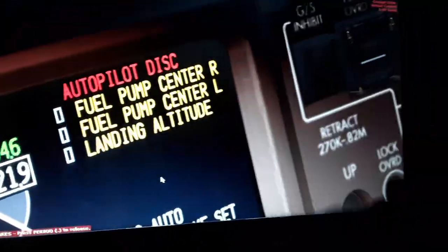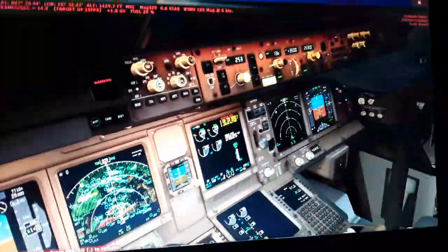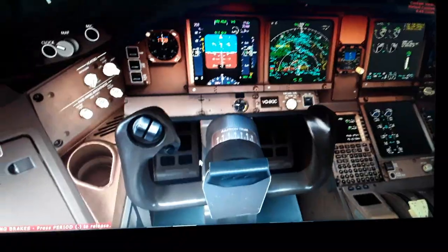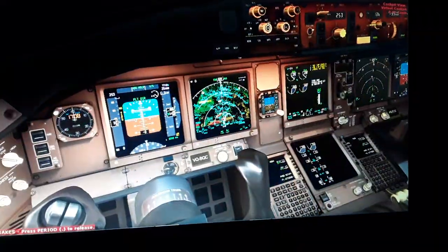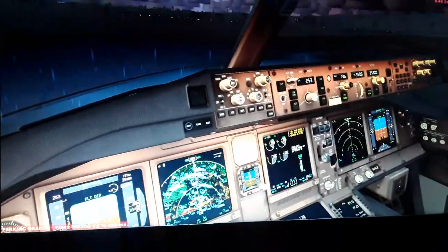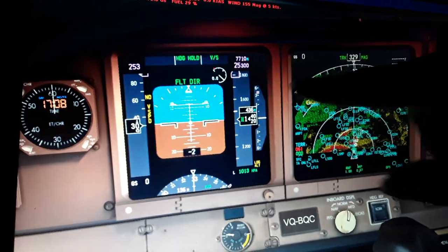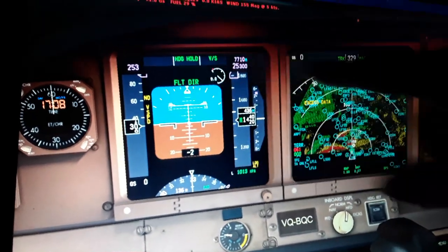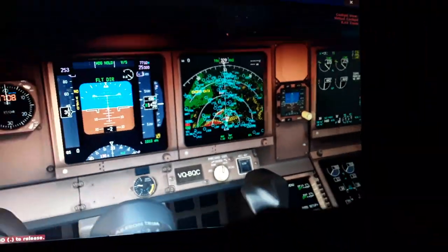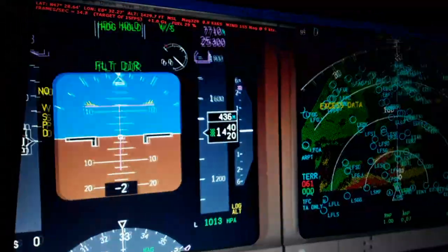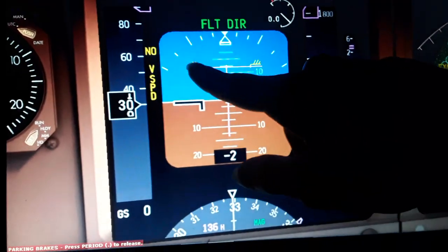Or you can move the flight controls to do that. And then press one more time here the switch. It will confirm the disconnect action and will cancel the warning. So now the autopilot is disengaged, and we have this mode with the flight director. Also the vertical speed with the flight director for this climb rate and this target altitude. So we have also, perhaps this is for picking up in the takeoff.